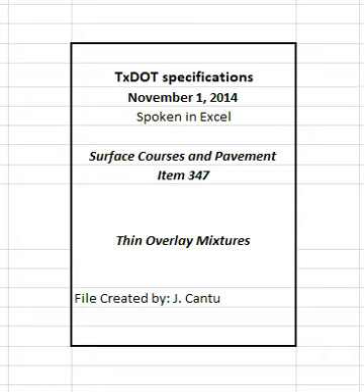4.7.1.2 When not using a thermal imaging system, place mixture when the roadway surface temperature is at or above 60 degrees Fahrenheit unless otherwise approved. Measure the roadway surface temperature with a handheld thermal camera or infrared thermometer. The engineer may allow mixture placement to begin before the roadway surface reaches the required temperature if conditions are such that the roadway surface will reach the required temperature within 1 HR of beginning placement operations. Place mixtures only when weather conditions and moisture conditions of the roadway surface are suitable as determined by the engineer. The engineer may restrict the contractor from paving if the air temperature is 70 degrees Fahrenheit and falling.